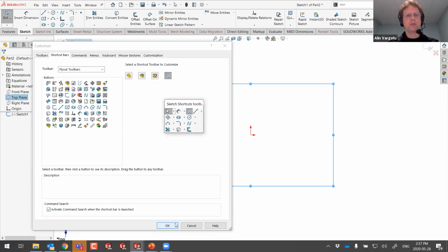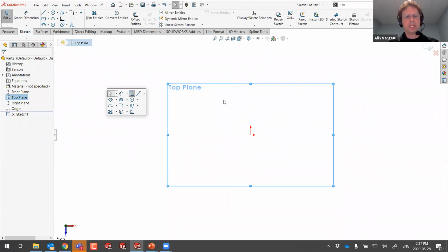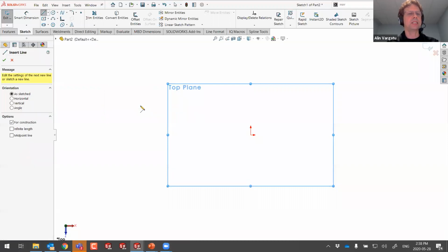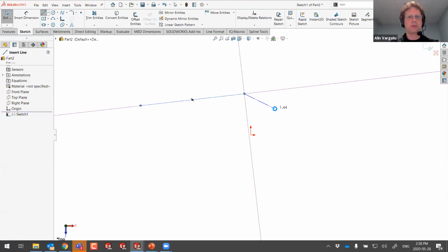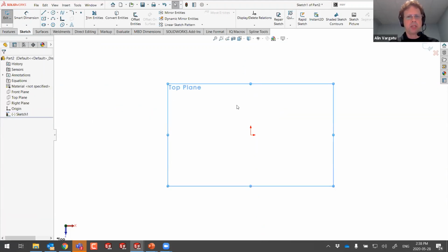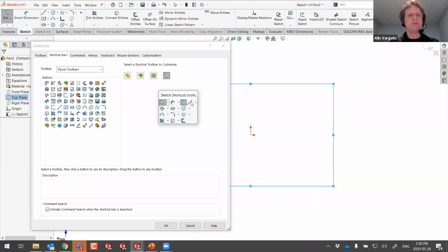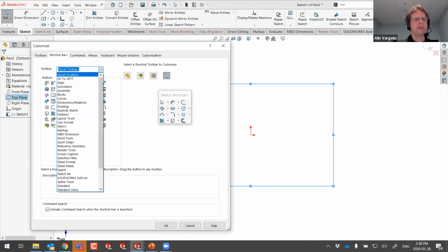Before I do that, I have another major point. By default, when you start with SolidWorks, you're going to get quite a few commands that have these little drop-down arrows, so flyouts. For example, for the line, if you want a center line, you have to do one extra click, which is pretty counterproductive considering how powerful and popular the center line is. Because of that, my recommendation would be to throw away the flyout for the lines and add the individual commands for line and center line. So if you're looking at the toolbars, the way they are set up here, the first one is about flyout toolbar.